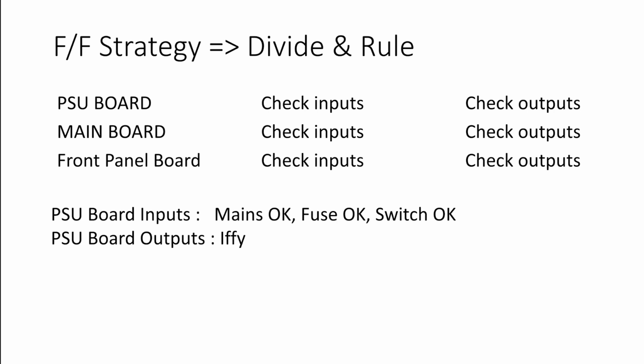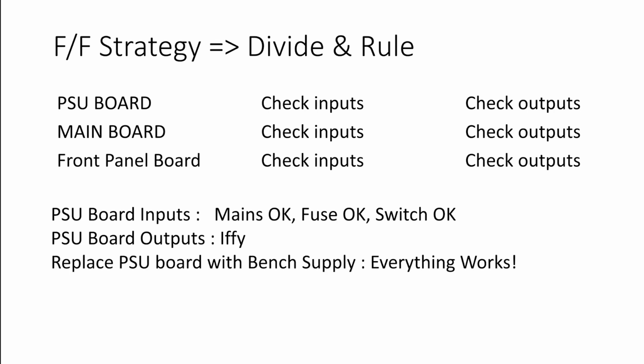substitution. I replace the power supply board with my bench supply. As you can see, I've got a bench supply sitting in the stack. So I simply plug the bench supply in place of the power supply board, set up the right voltages and switched it on. And lo and behold, everything works.